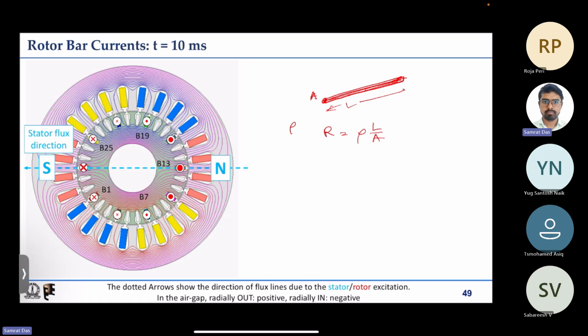inductance also. Why inductance? Because for any copper bar, or for that matter any conducting thing, if some current flows, then there will be some magnetic field around that, and the magnetic flux lines will be enclosing that conductor, enclosing that bar, strip, whatever conducting body we have. That means there will be some flux linkages inevitably for any conductor, and the flux linkage will scale with current.